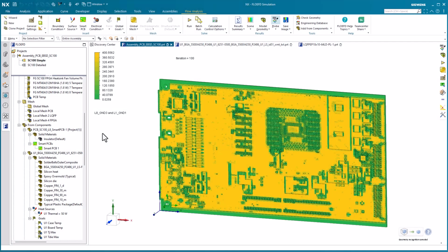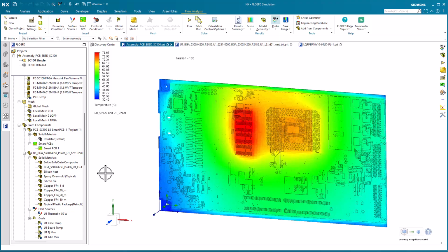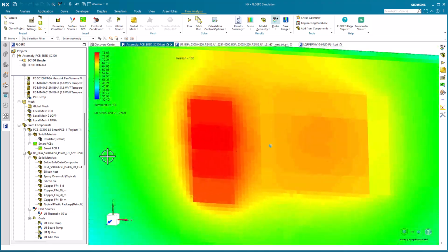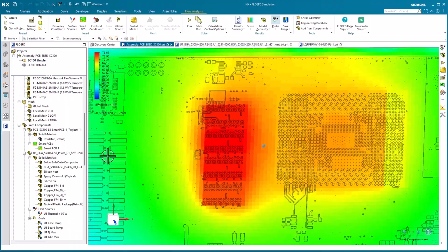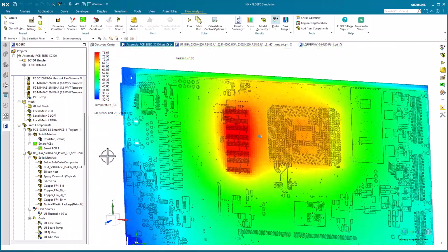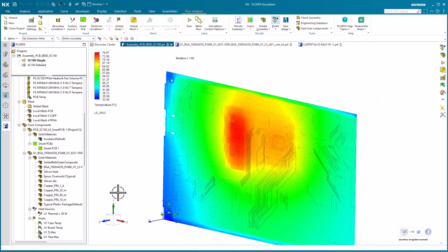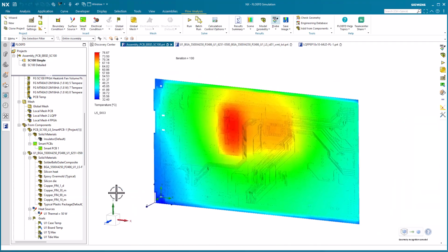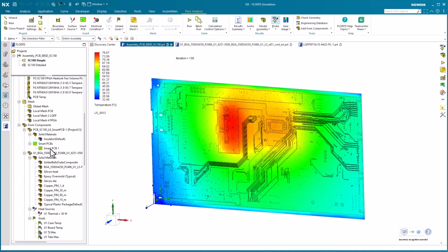As the PCB is a thermal resistance matrix, we can report the temperature within the board and check individual layers for where the hotspots are. We can see a roughly 76°C zone under the RAM modules, which is well within acceptable limits. We can check internal layers to ensure good heat conduction and feed back this data to the ECAD team, as high temperatures can affect power and signal delivery.